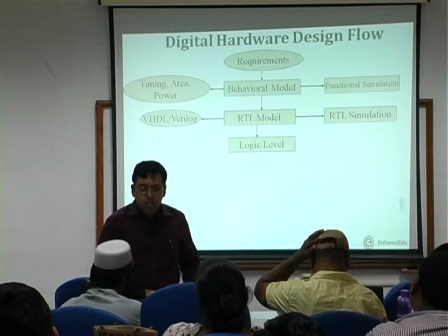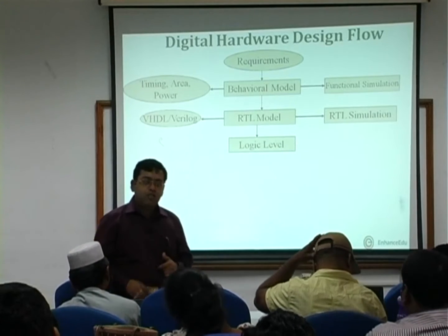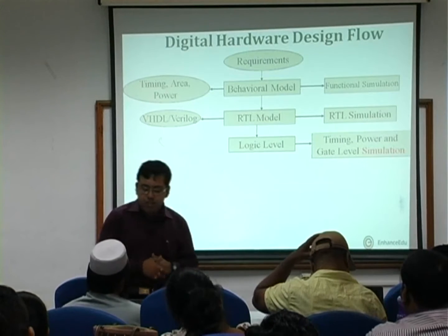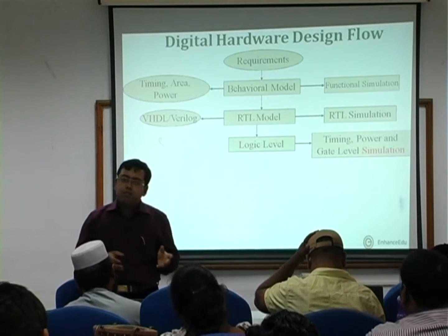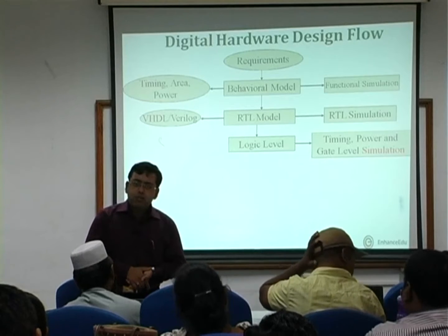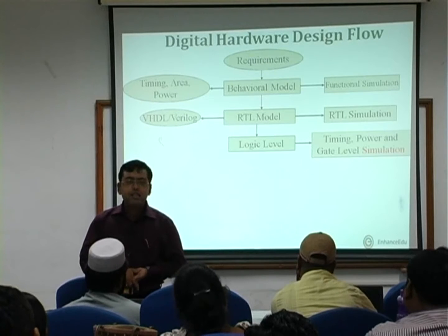The RTL model is then translated into an interconnection of logic gates, which we call the logic level model of the system, and therefore now you can perform accurate power estimation, then timing considerations. So power estimation, how can we make it at the gate level? Can you give me any idea?